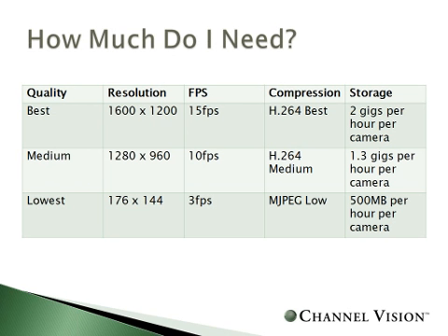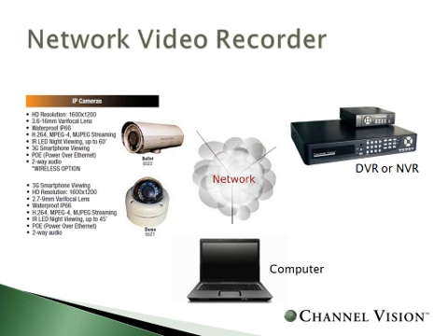Your other alternative is integration with a network video recorder. With a network video recorder, essentially your cameras plug into the network, as does the network video recorder. And then you can view both your camera and access the network video recorder from your computer. Typically, IP cameras use a standard known as ONVIF, which implies that they can all work together nicely.